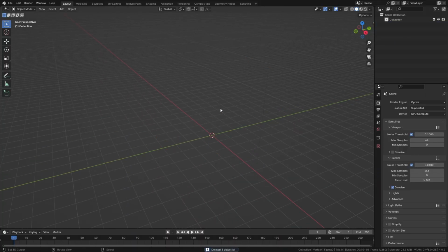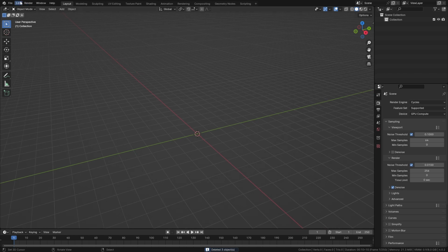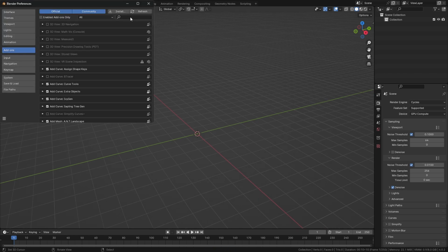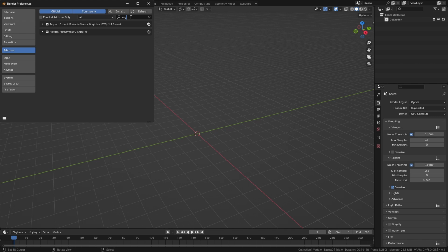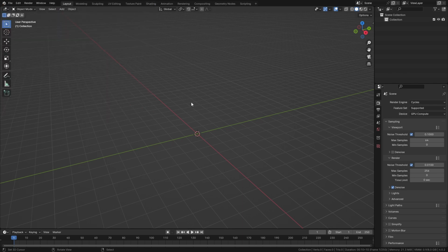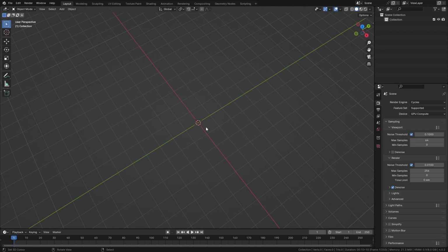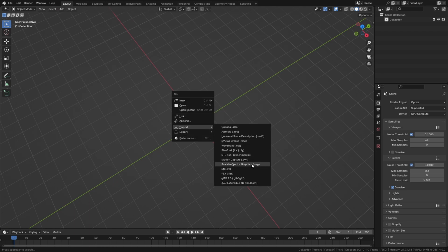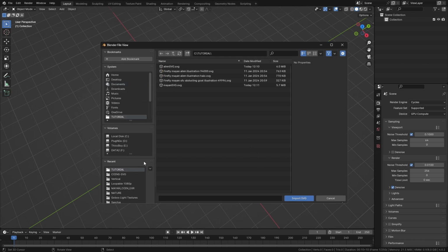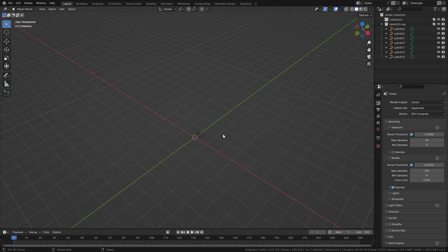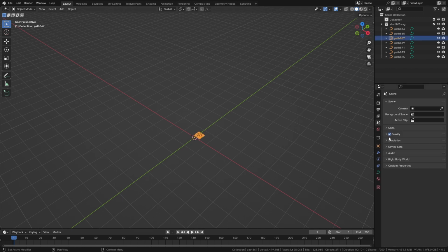Next up, what we do is open Blender, and we have the default scene. Take everything and just throw it in the bin, delete it, and we're going to go to preferences and just enable our Bool Tools and SVG add-ons, because that is very crucial, because we want to put in an SVG file. So what we do next is press F4 for the shortcut key to get to the import menu, the bottom one, not the top one, not the grease pencil.